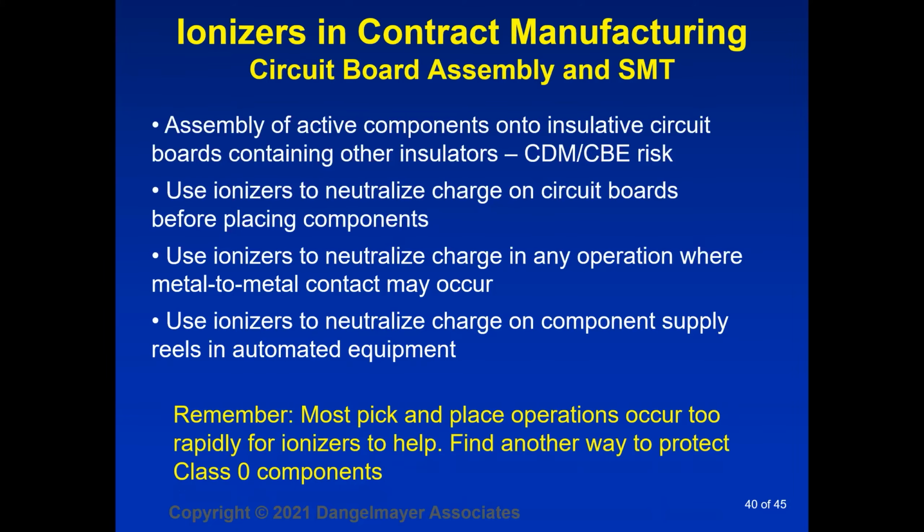Remember, most pick and place operations occur too rapidly for ionizers to help. Ionizing inside the pick and place machine rarely has any effect that you can measure. You need to find another way to protect the class 0 components.